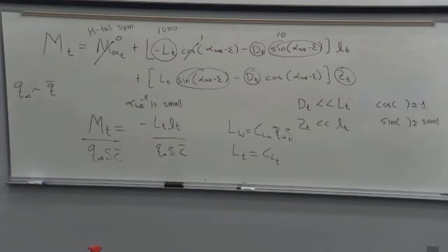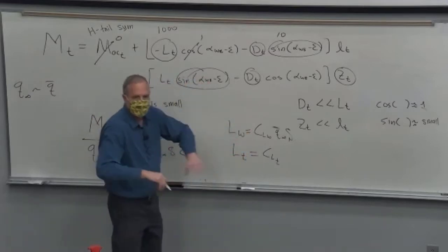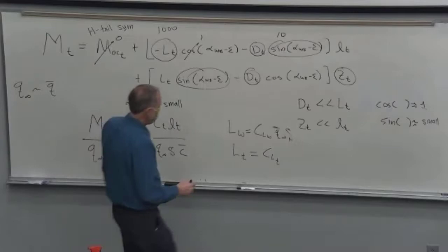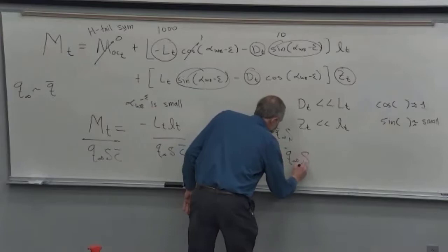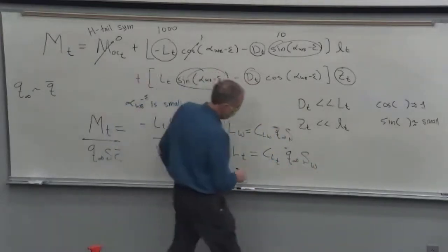Absolutely nothing, right? In fact, if we were going to calculate the lift curve slope for the tail, we'd use that big formula you guys just did in the quiz. And all of the information that goes into that is the airfoil data for the tail and the area of the tail and the aspect ratio of the tail, just for the tail as if it's its own flying wing. It's just a wing in a flow. And so by definition, we have to multiply this by the area of the tail to get the lift. Why did I write that? Tail, sorry.